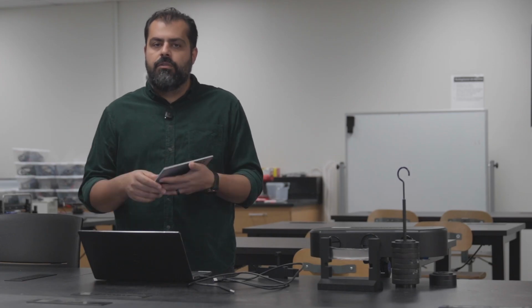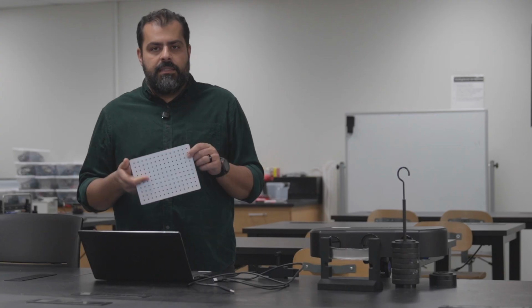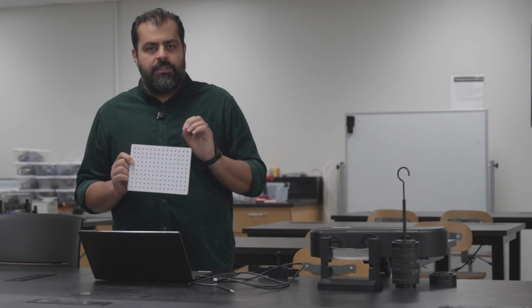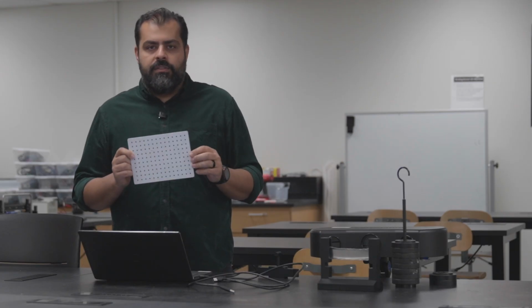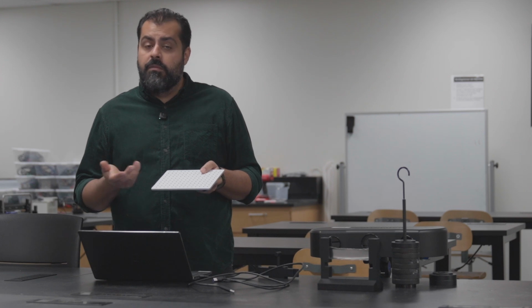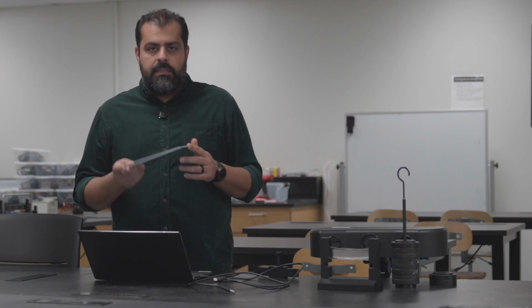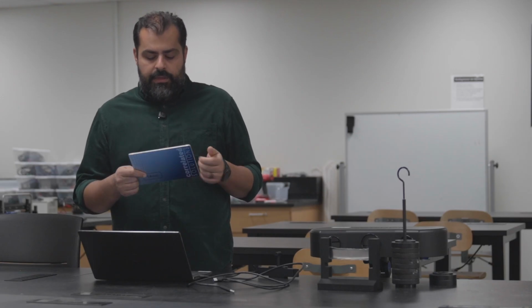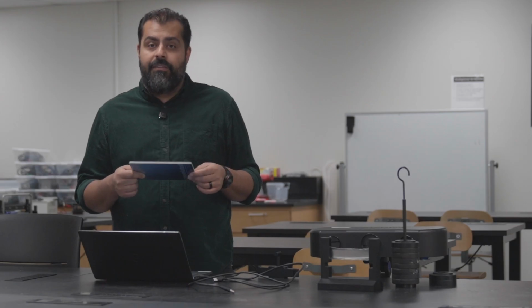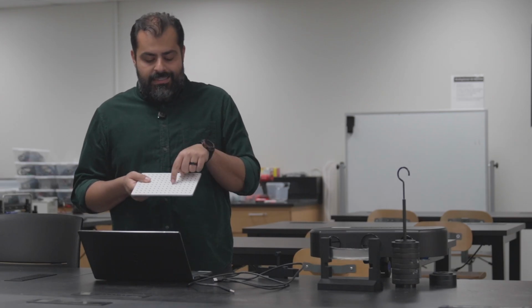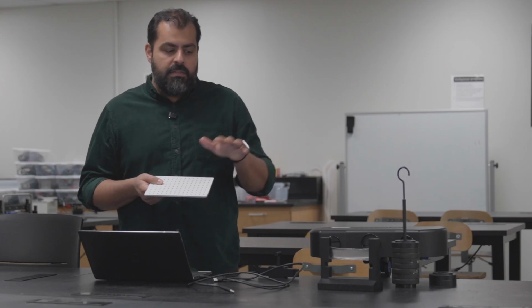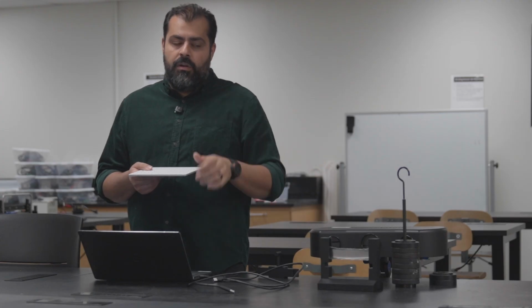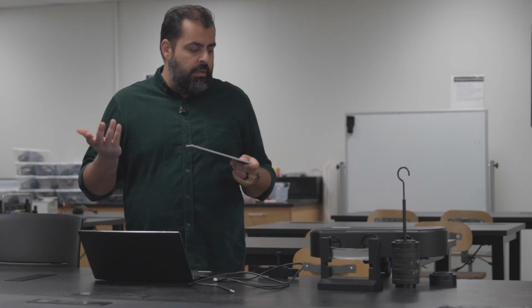So what we're going to do is take a couple of pictures of this, as many as you need. Usually 5 pictures are fine, and I put a strong emphasis on usually. A lot of times you need to take more than 5 pictures, right? With this, and using the 14 millimeter measurement that we already have, we are going to tell the software that these are 14 millimeters apart. This way, the software is going to know how far apart your speckles are on your sample. Okay, so a brief introduction.